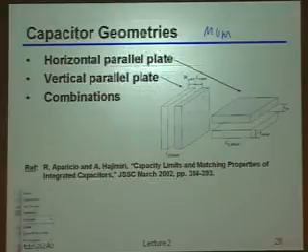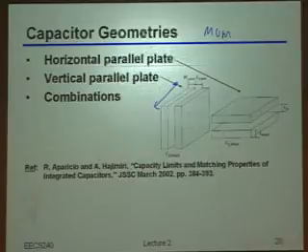So you said, in some senses, the only thing I can really control is the length, right? Now, that's not exactly accurate, but what you're saying is very true once I do a little bit of optimization. So if I wanted to, what things could I potentially control? Spacing? Yeah, okay, so I could potentially control this spacing here, right? I could also potentially control the width of that line there, because the width and the length are still in the layout dimension, right?